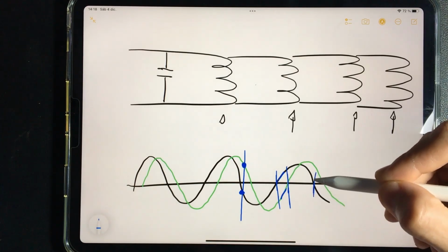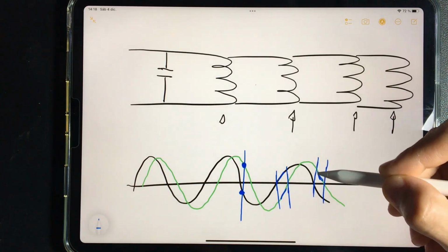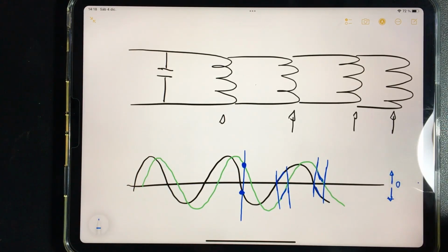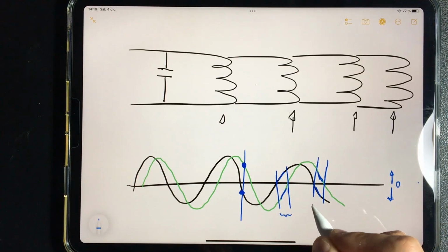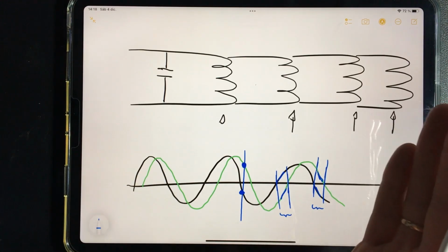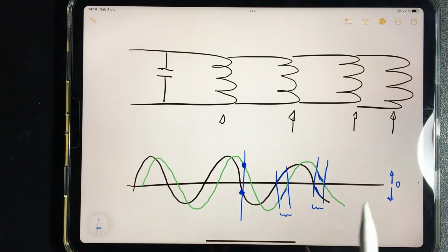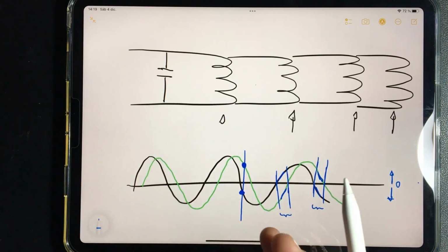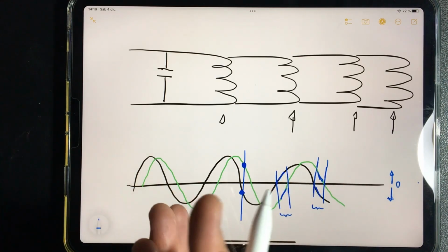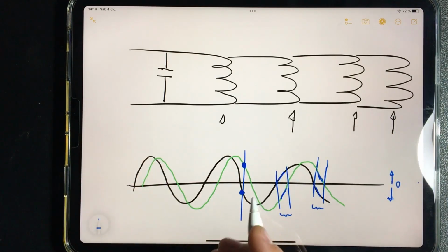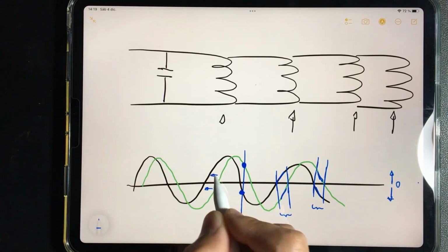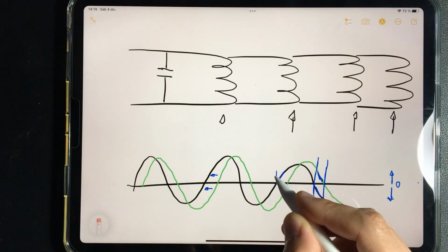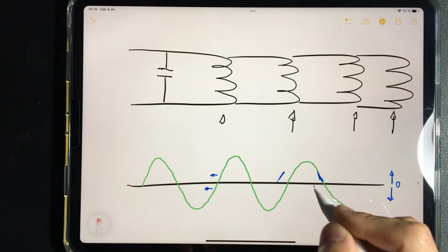But here again it hurts us again. You see that it is towards one side and towards another, always from this line, I mean, which is voltage 0. There are moments in time when the voltage is pushing to one side and the coils to the other. What do I do to compensate for this? What is done is to place capacitors. So what I do is delay the voltage a bit that was advanced by the coils, and then I equalize this line and this line, I take it to that side, and we tend to equalize it exactly. There it went too far.